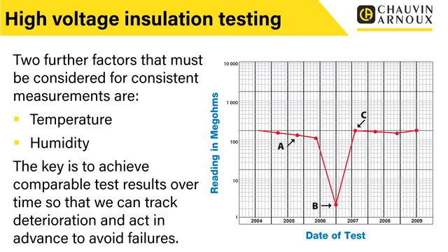So that's a big change. The insulation resistance decreases as the temperature goes up, and it actually makes a big difference. A 10-degree change in insulation temperature can actually halve the insulation resistance. So it makes a big difference to the measured insulation resistance, and we have to be aware of that.